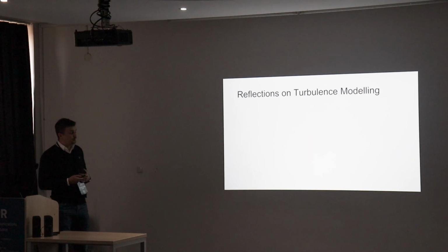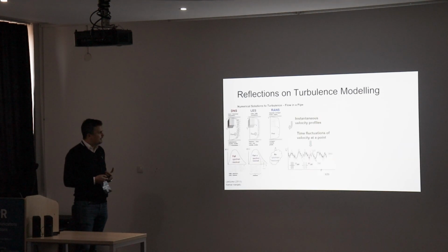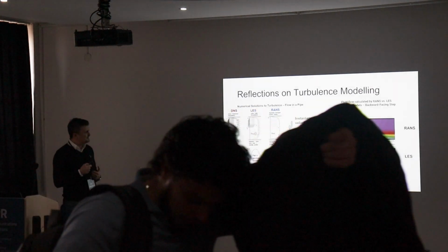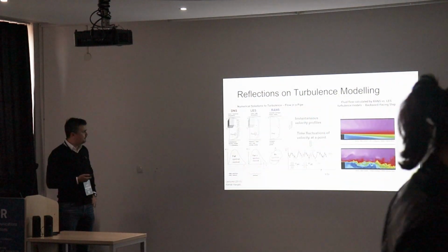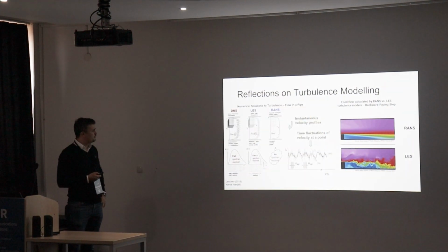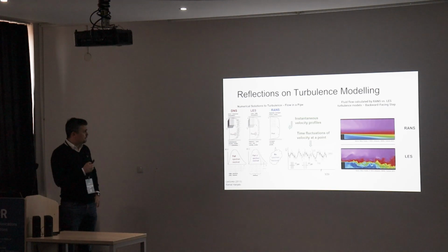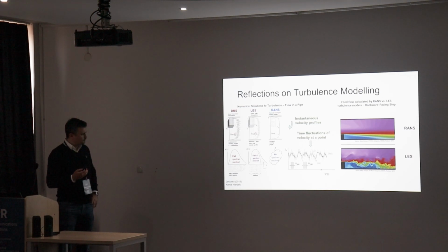To describe turbulent motions or turbulent flows in CFD, we have different approaches. For example, we have the Reynolds-averaged Navier-Stokes approach, the large eddy simulation approach, and the direct numerical simulation approach. The essence of all these approaches is how to describe the energy spectrum, or turbulence spectrum.